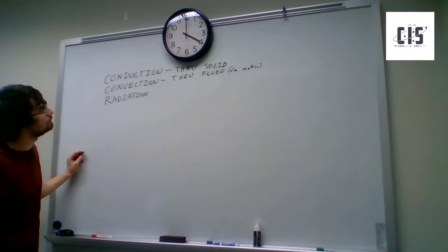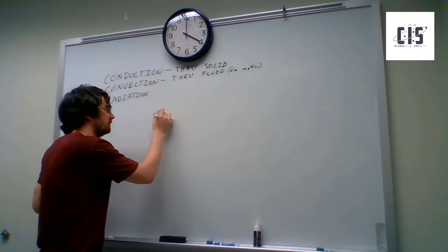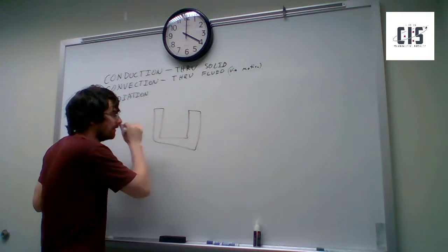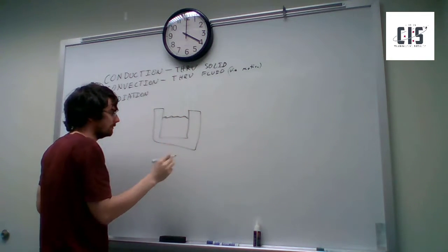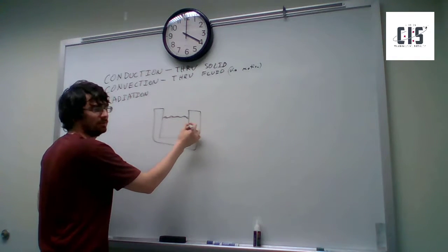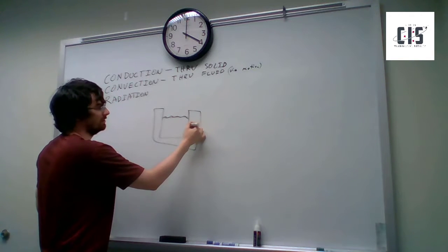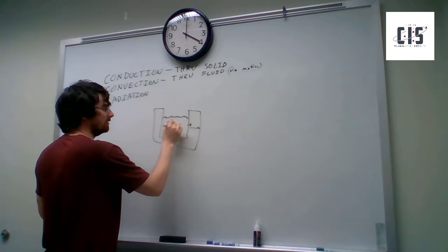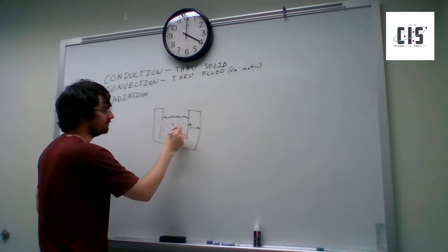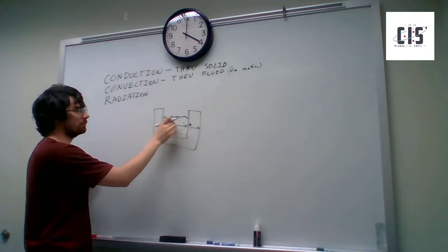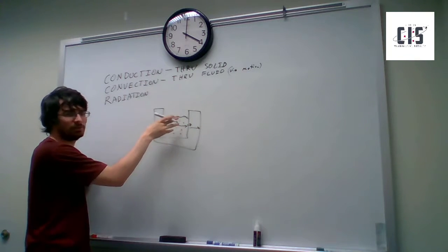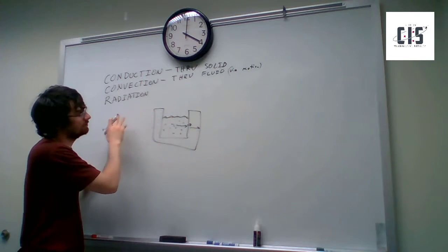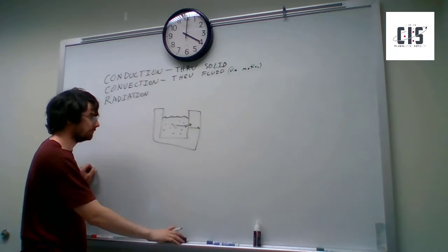So would a good example of that be if you pour coffee in a coffee mug, and then it raises the temperature through convection, or would that be conduction? If you have a coffee mug, let's just draw a mug here. Great mug. At the surface there's going to be conduction into it, and then through the coffee mug there's also conduction, but then inside the liquid it is convection. So the process of heat evening out through the liquid is the convection. Okay. So it's a mixture, as the edges cool, convection is also occurring. Yes.